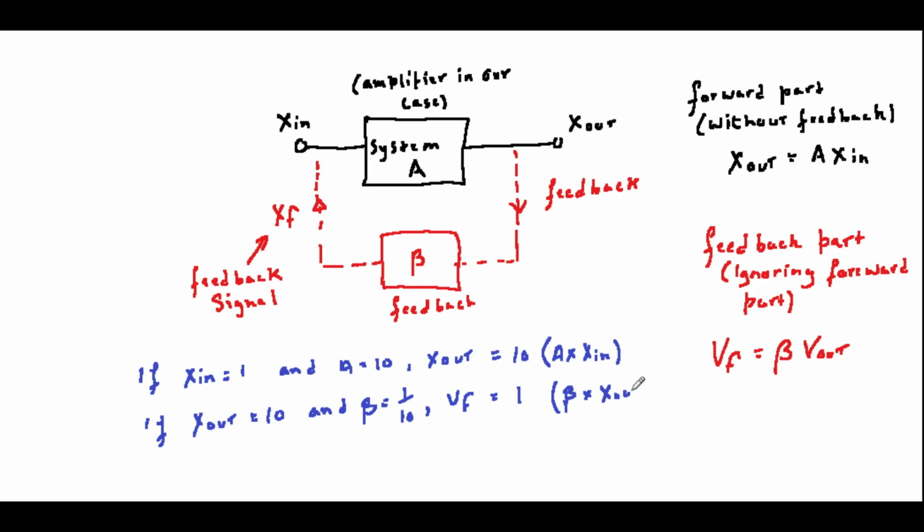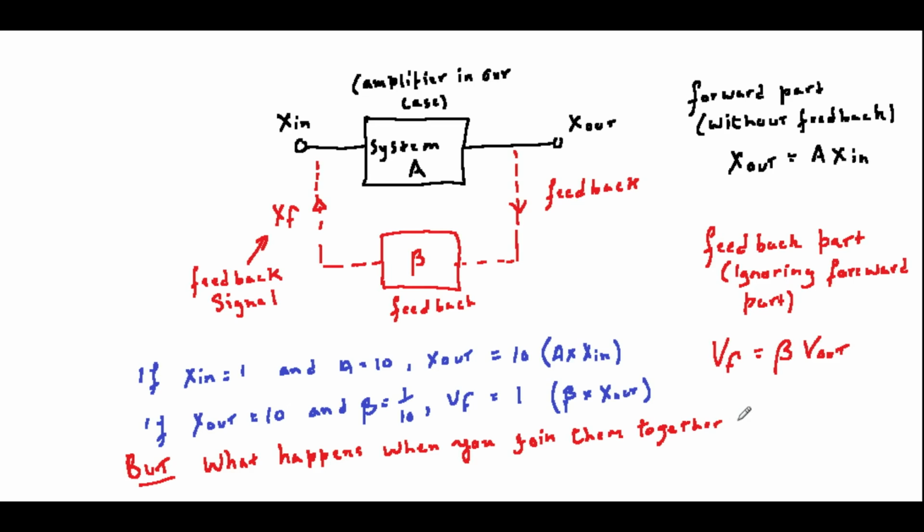Negative feedback decreases the gain of the whole system, but also makes it more stable. It also has a good effect on other properties of the circuit, reducing noise and increasing input impedance and reducing output impedance. Because of this, negative feedback is very useful in amplifiers.